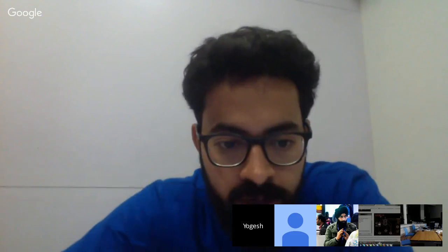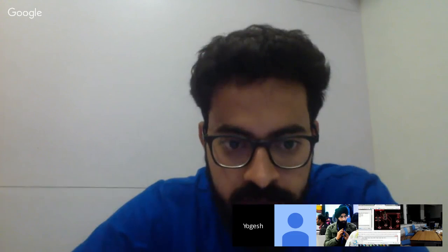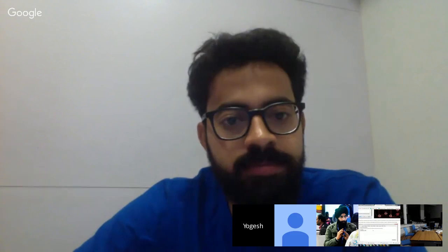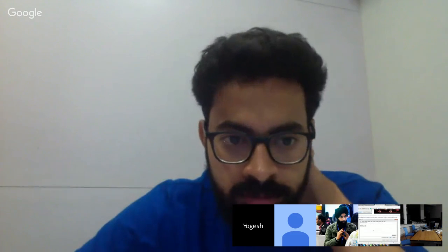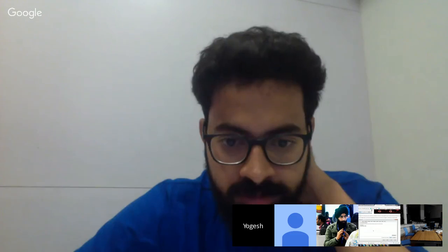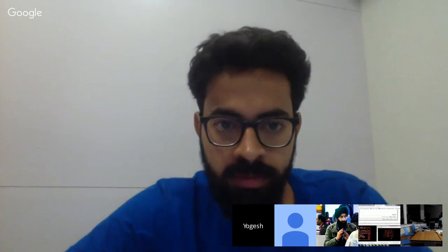So there is one more command, DRC. Yeah, then came something new, which was DRC, where I was completely lost because I did not find the DRC or the design rules for the same. So after downloading that, I realized that what I had checked earlier was incorrect, and now I'll have to do it with the Fab design rules. So I incorporated that in the Eagle software and again did a check.